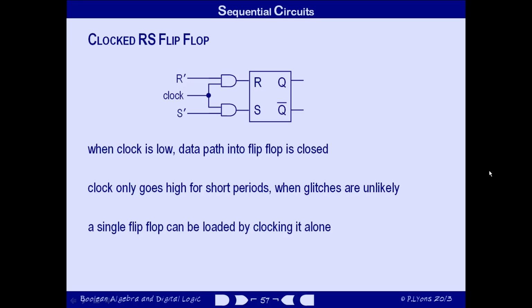The clocked RS flip-flop has been used in commercial computer designs. However, glitches can't be eliminated altogether, and as computers got faster and smaller, the frequency with which they occurred increased to the extent that the probability of corruption of the data became unreasonably high. And there seemed to be too many wires going into the flip-flop. We only want to be able to load a bit of data and store a bit of data. Surely three inputs is too many. Something, as they say, needed to be done.